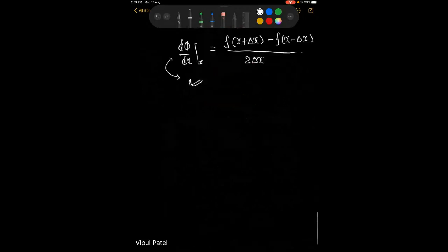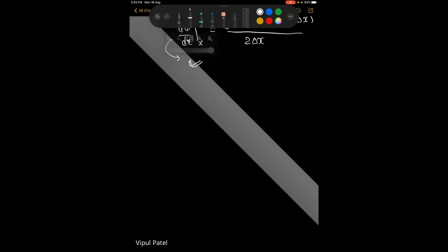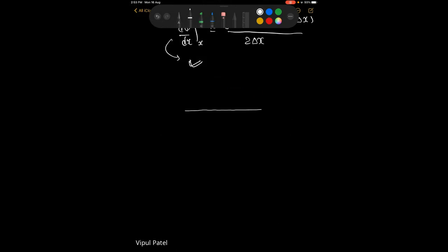But before doing that, let us try to understand what we have covered so far in terms of a one dimensional steady state heat conduction problem. Then I'll explain how you can derive a higher order accurate scheme. So let's suppose this is a one dimensional heat conduction problem. This is a boundary at x equal to 0, this is a boundary at x equal to L, and let's suppose we are implementing heat flux equal to 0, or you can say an adiabatic boundary condition, on the left hand wall, and the right hand wall is maintained at some constant temperature that is equal to TL.